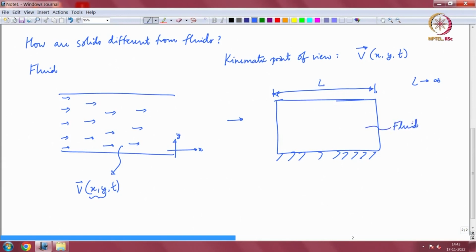If you want to get a flow in the fluid, there are usually two configurations that you have probably seen multiple times in the fluid mechanics course. The first is of course you can apply a gradient in the pressure in the x direction. Again this is x, this is y, the origin of coordinates does not matter, and you can apply a pressure gradient. So, if the pressure here is P1, pressure here is P2, and you have P1 not equal to P2, then you can get the fluid to flow either left to right or right to left, depending on which one is larger, right. So, you get a flow in response to a gradient in the pressure.